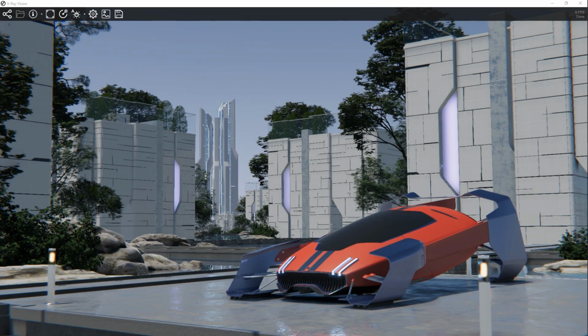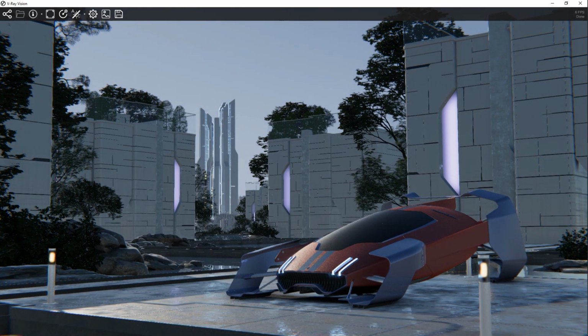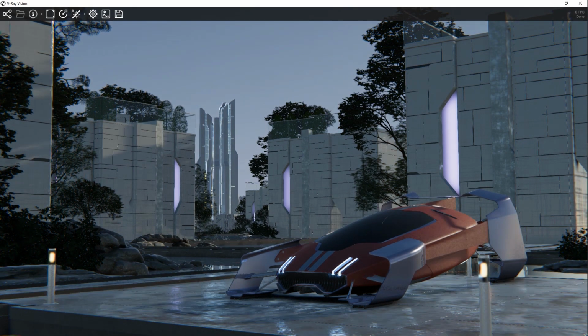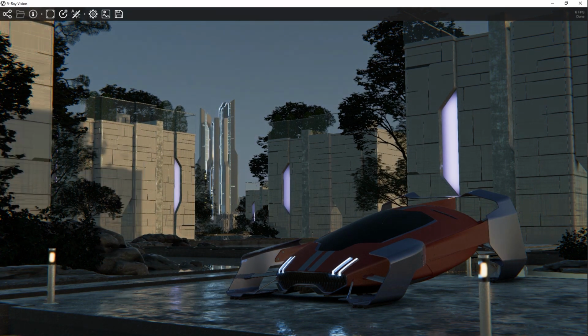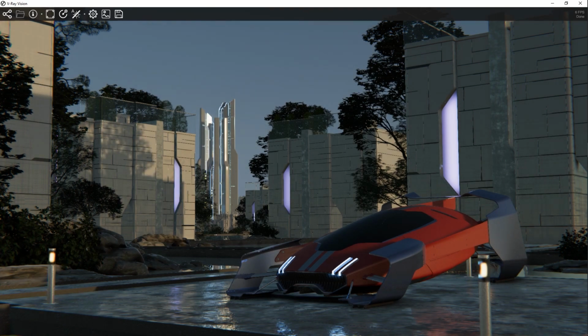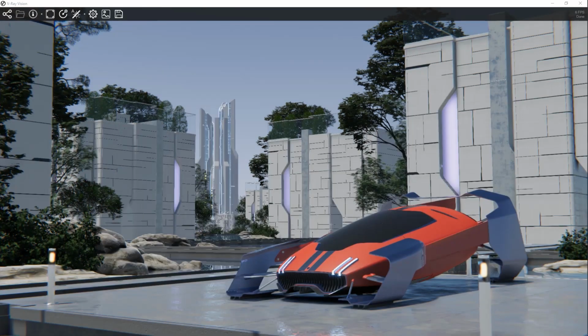Alright, now let's take a look at adjusting the lighting here. You'll see that we can easily tweak the sunlight's direction by holding Shift and using the left mouse button to control its altitude when going up and down, and to control the azimuth when going left and right. The sunlight adjusts right away, allowing us to find an ideal position. You can even hold Shift and drag the right mouse button to adjust the sun's intensity up and down. Also, at any time, you can press F5 to reset the sun position and the lighting changes, so as to match the original scene state.